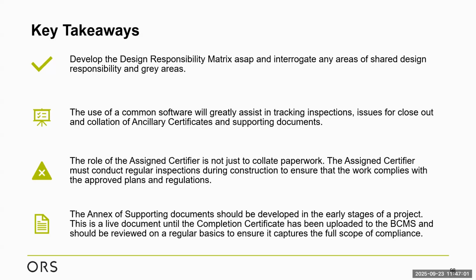I mentioned this before, the use of common software greatly assists in the tracking of inspections, of issues, and the collation of the auxiliary certs and the support documents. These software packages allow you to populate it, you can assign responsibility, you can assign a reviewer. That all adds to the ease of collecting this documentation. The role of the Assigned Certifier is not just to collate paperwork. The Assigned Certifier must conduct regular inspections during the construction to ensure that the work complies with approved plans and regulations.